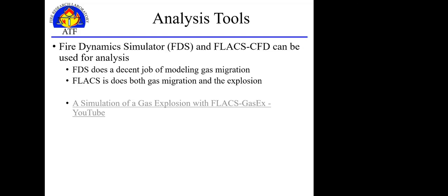Yes or no, that's not an acceptable fuel source. We can also identify how long, given a certain sized leak rate, if we've done leak testing in the field and determined that there's a certain size leak, we can punch that into a spreadsheet and determine how long it would take to get to an explosive mixture, given that leak rate and certain air exchange rates of a structure.